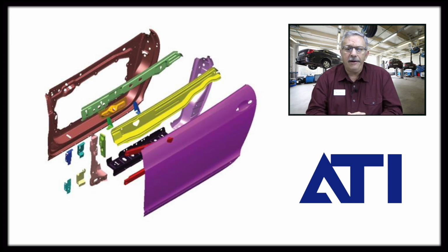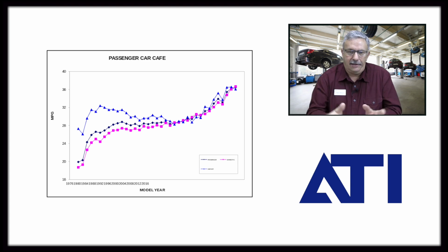And now the aluminum and the new lightweight composites together give us the same strength as steel, but at a much lower weight, because there's something called CAFE, the Corporate Average Fuel Economy Act. It's been in place for a number of years. There are specific miles per gallon targets tied to the weight of the vehicle and the size of what's called the greenhouse, where the passengers sit. So it gives us a weight ratio to fuel ratio that we have to meet.